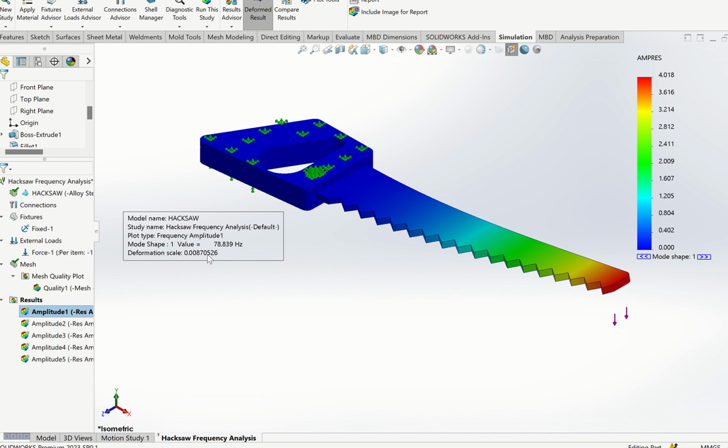You will get 12.55. That is our fundamental frequency. So our fundamental frequency will be 12.55. If you are doing analytical calculations, you do analytical calculations and then compare with the software. How will it vary? If they are close to each other, then it means you have done what you call design analysis. That is a design analysis under vibration analysis.